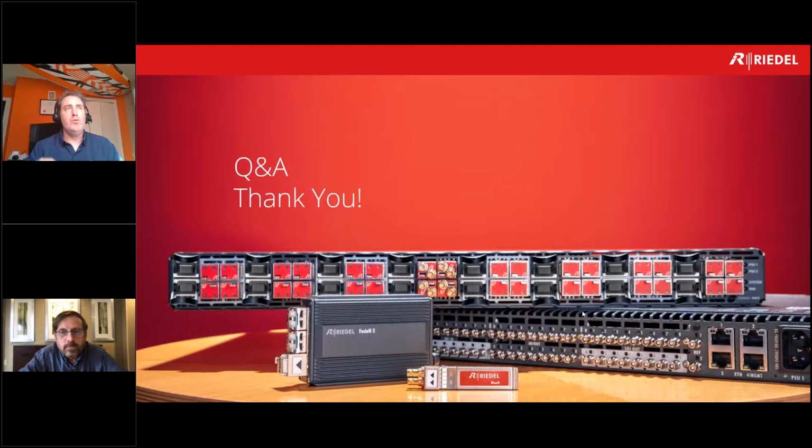Yeah, that's correct. If you want to keep a good quality, it will be visually lossless. You can go close to 10:1. If you're more on a monitoring or return feed, you can go to 20:1, from my understanding. This goes beyond JPEG XS. This is what they will call TICO XS, which is not an add-on, but more compression you can achieve. But you will see some degradation of the picture. And the other thing that's incredible is the low latency, right? Because it's line based, not frame based. It's about 21 lines back to back. That's pretty good. That's a good number to remember.